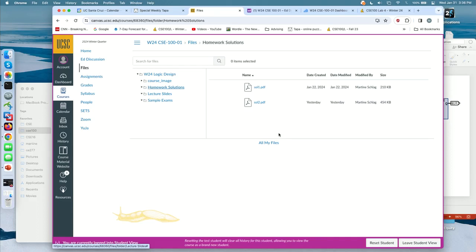Yes? This is kind of a conceptual question. When you're doing a SOP K-map and you have don't cares, do you circle the don't cares too, or is it just the zeros? So you mean when you do the product of sums? Yes. When you do the product of sums, you are basically just swapping ones and zeros. So again, you would cover the zeros and the don't cares. So again, you treat the don't cares as ones too. They're wild cards, right? They help you.